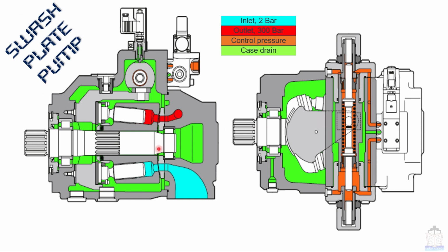This is the picture of a swash plate pump. The first picture shows that the swash plate cam position is at 0 degree angle. So cam angle equal to 0 degree, no pressure buildup in this situation. In the second picture, it is showing that the cam is at its maximum position, and in this position maximum pressure buildup is possible. Here some parameters are given.